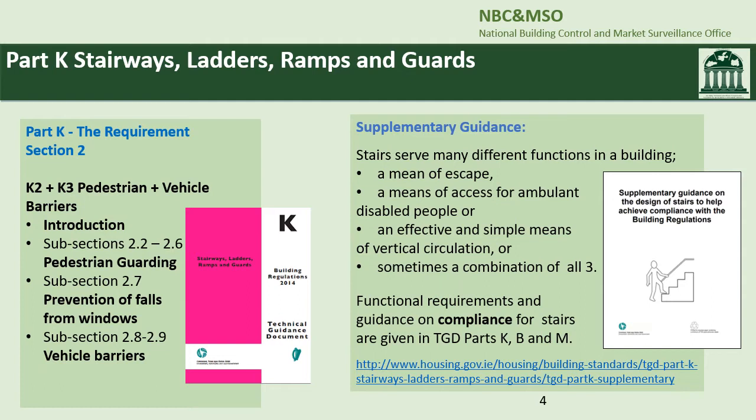The requirements of Part K2 and K3, pedestrian and vehicle barriers, are covered under subsections 2.2 to 2.7 of Part K TGD, pedestrian guarding, subsection 2.7 of Part K TGD, prevention of falls from windows, and subsection 2.8 of Part K TGD, vehicle barriers. The Department of Housing has published supplementary guidance on the design of stairs to help achieve compliance with the building regulations, which gives guidance on compliance issues in relation to TGD Part K, Part B, and Part M.